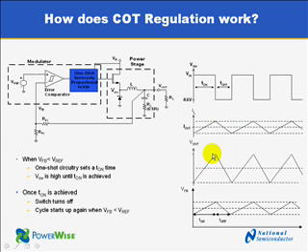The voltage at the feedback pin is still tracking the output. The next on cycle will not be initiated before the feedback falls below the reference voltage. Overall, we end up with a fixed frequency with a duty cycle dependent on the ratio between the input and output voltage.